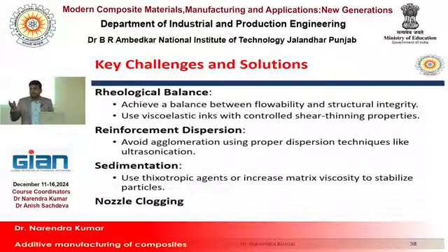So in our case, what is the size of the nozzle, Vivek? 0.1 mm? 0.1 mm. So 0.1 mm is very small. Suppose the filler particles are agglomerated inside the resin. So their size may increase, right. So they will block, or clog, the nozzle. So this is one of the issues.